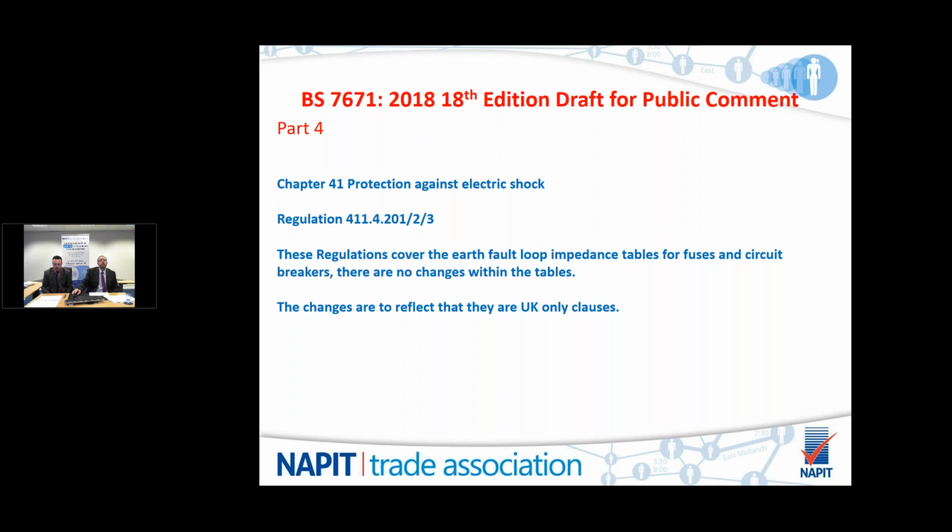Okay. Regulations 411.4.201, 2 and 3. These are the regulations that cover earth fault loop impedance tables for fuses and circuit breakers. There are no changes within the tables, but the changes to the regulation numbers reflect that they are UK only clauses.